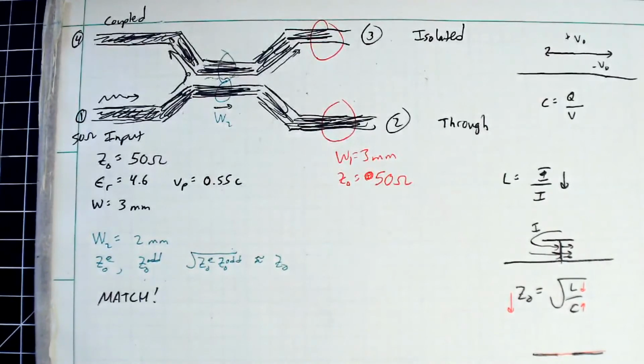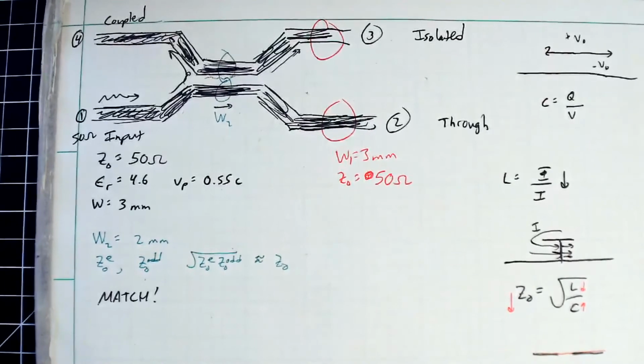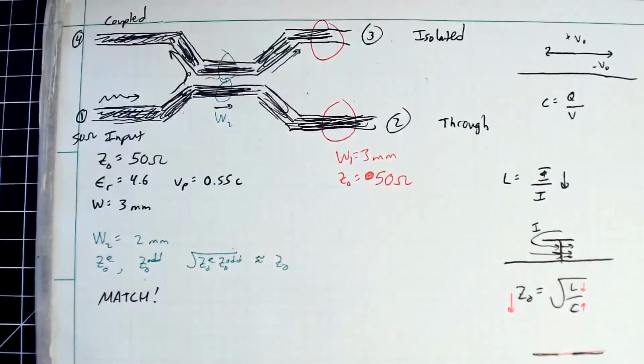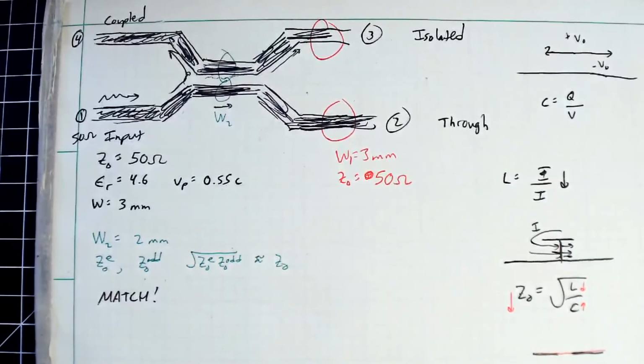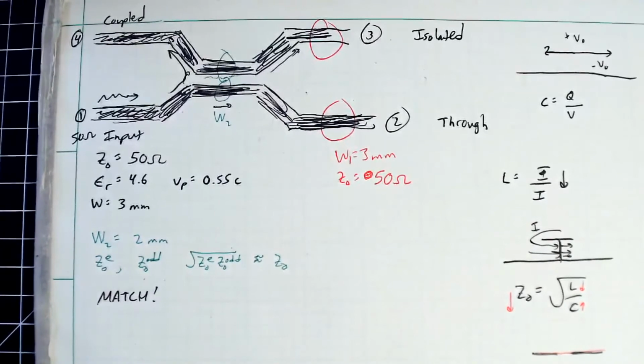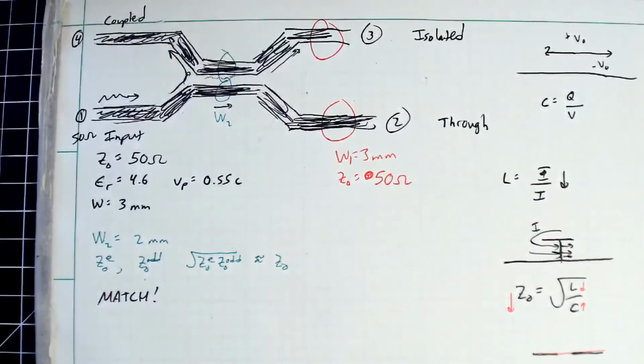In fact, I can do even better than that. So you notice, yeah, that barely changed it by like an ohm to do that. So let's shrink it in even more. So now they're just really cramped. And I might even blow up the simulation now because it needs to do a Gaussian contour in between that little bit there. So if you do it too close, there won't be enough grid samples to do the calculation properly. We'll see there. So that might have made an effect. Let's do one more double sanity check here. Just to make sure there's some grid samples in there.